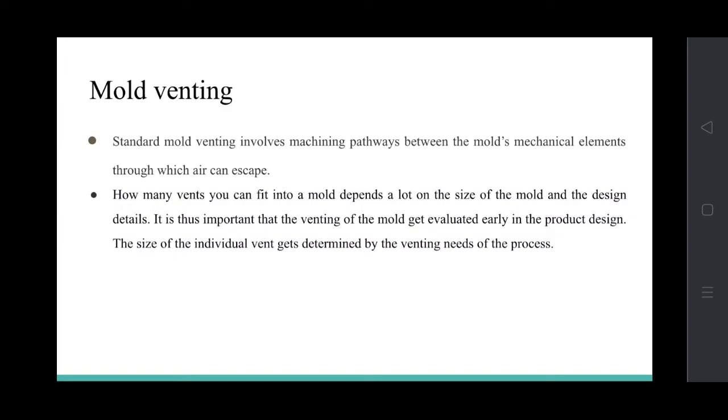The last one is the mold venting. Injection mold venting slots serve two uses. The first is to remove air from the plastic injection mold cavity during the molten plastic material injection process. The second is to remove the gases produced throughout the injection molding process. Venting slots must be strategically placed, especially for thin wall goods and for areas far from the gate. Venting slots for small sizes or exact spaces should be carefully considered as well, as they can protect the goods from surface burns, insufficient filling, and other issues.